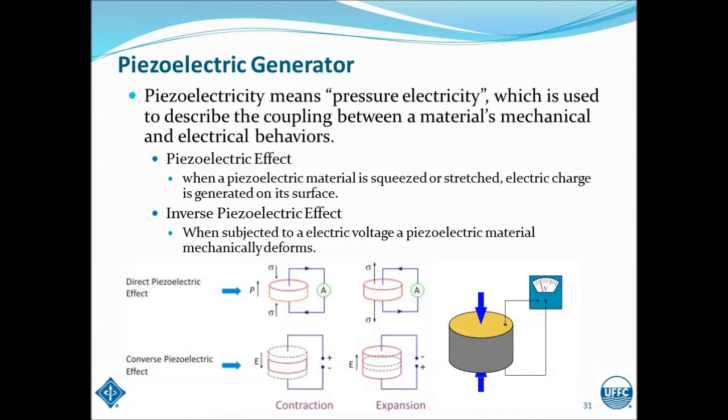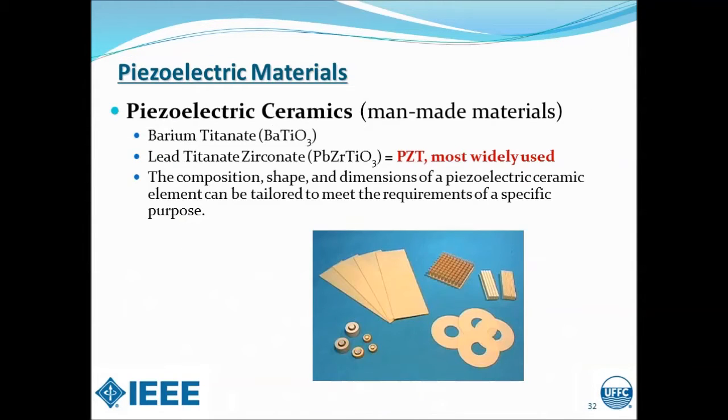Piezoelectric generators. Piezoelectricity means pressure electricity, which is used to describe the coupling between a material's mechanical and electrical behaviors. The word piezo comes from the Greek word piezein, meaning squeeze. The piezoelectric effect is when a piezoelectric material is squeezed or stretched, an electric charge is generated on its surface. The inverse piezoelectric effect is when it's subjected to an electric voltage, a piezoelectric material mechanically deforms.